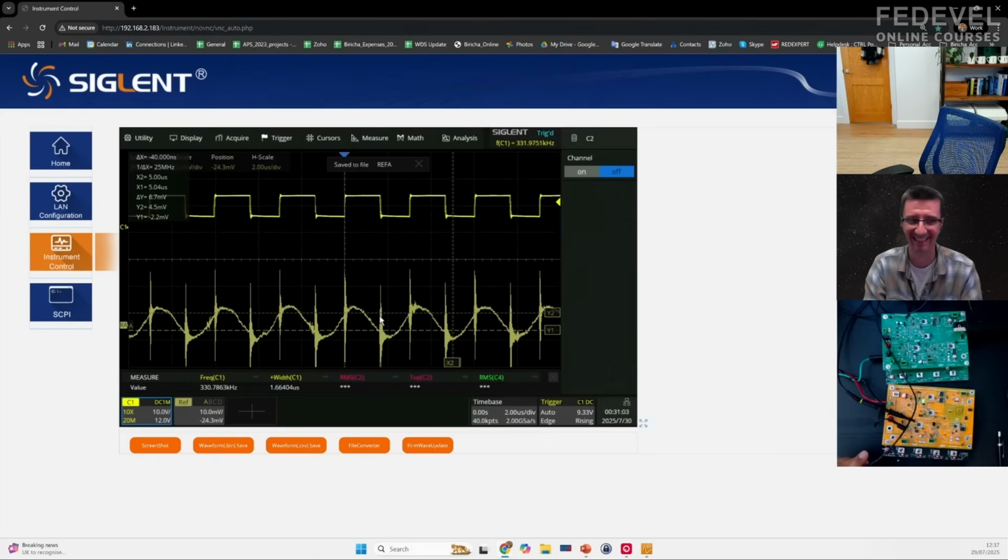Okay. Now, for an electrolytic capacitor, the ESR of the capacitor is very, very big. So the ripple that appears across the electrolytic capacitor is predominantly due to resistance. And of course, if you put a triangular current through a resistor, you get a triangular voltage out, right?